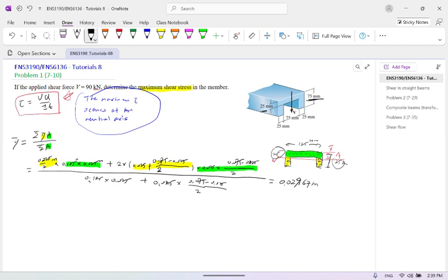So this is the basic thing. And we need to work out the I as well, because the structure is this structure. We know the structure here, so we should know how much the I is. Of course, we should use the parallel axis theorem. We mentioned these things. So that means Ix is equal to IxC plus A d squared. Clear? That's from the previous one. Okay, from here we can work out the numbers.